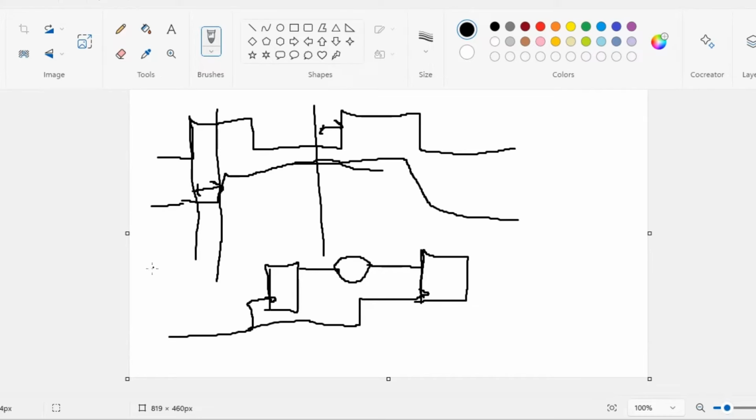One of the nets is this one. In parallel, one of the other nets is also sitting here. So what will be created in between? Anyone know? That's crosstalk. Yes, and crosstalk will create some distortion in the clock signal.